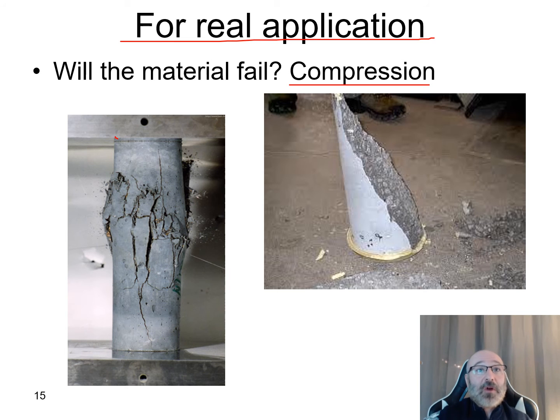We know at the beginning the diameter of this core sample that we took of the concrete. And this is a prime example of where we might not be able to look this up, especially for different types of mixes. We might want to get information from these compression tests to draw out our material properties for this particular mix. This is also something where maybe we're looking at a bridge deck, and this is a lot of work that I've done in the past.